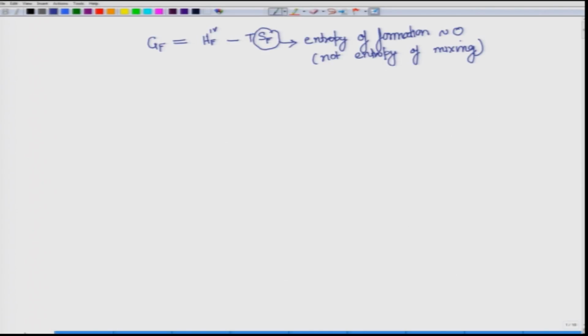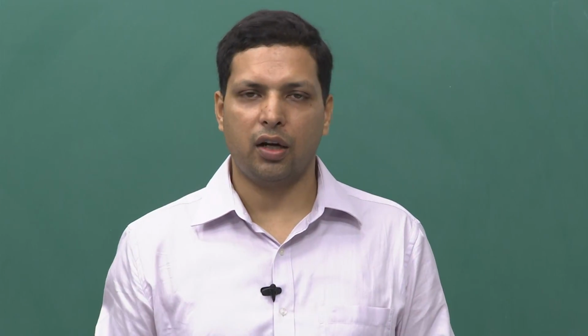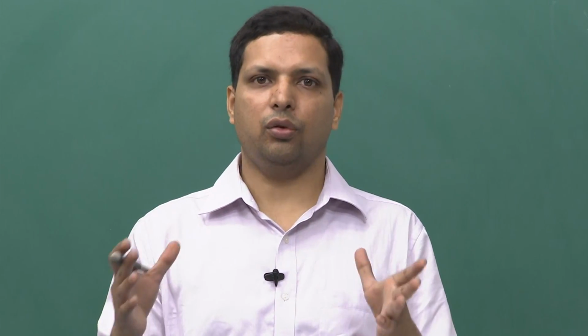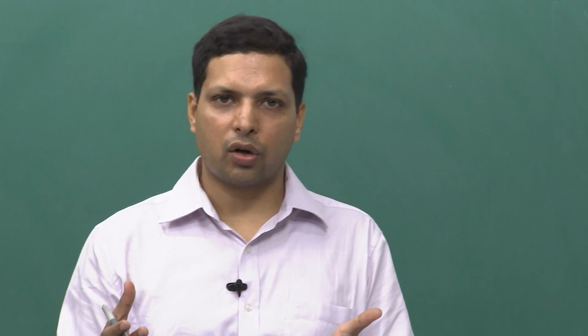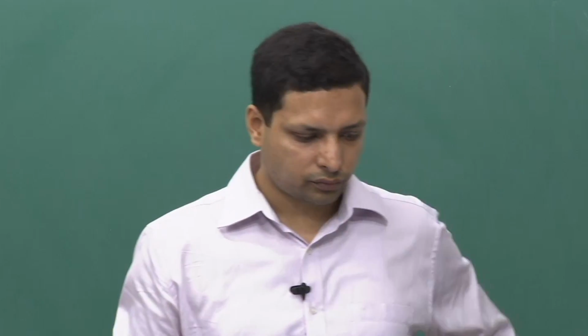Now, our next step is that since there is energy reduction with the formation of a vacancy, there will be more and more vacancies getting formed. So, what is that equilibrium concentration? Because as you keep increasing the vacancies, there will be change in the entropy of the overall system. Where is that change? When you do the mixing, there is a configurational entropy, or how many ways you can mix, and it reduces the overall energy of the system.